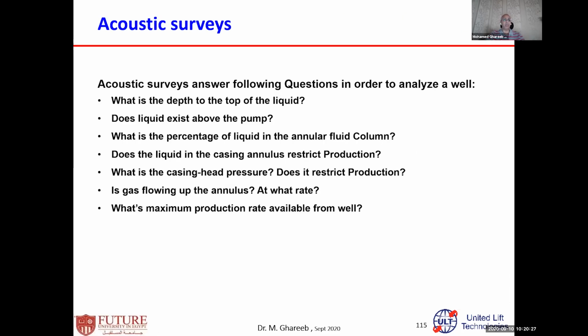Acoustic fluid level can tell you the depth to the top of the fluid. It can inform you if there is fluid over the pump or not. If there is, how much fluid is in the casing. Is the fluid in the casing gas or just liquid, or gas and liquid? If gas, how much gas? Because they use a special technique in order to determine this.